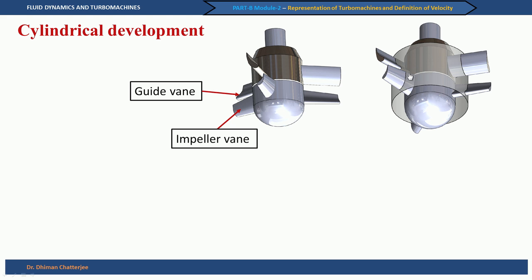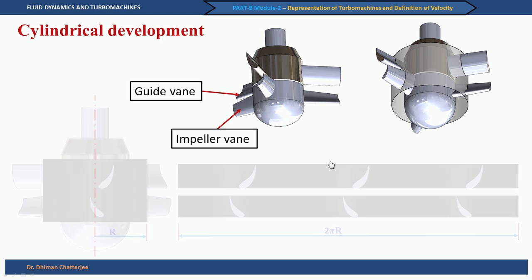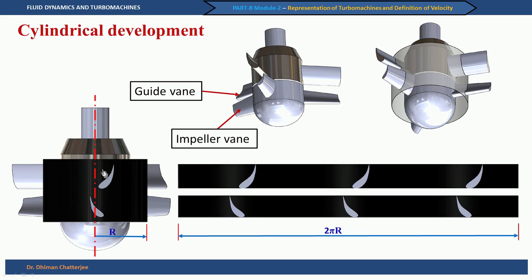To look at it more closely, this is a portion of the paper just shown, which is wrapping around the axial flow machine, and when the blades cut and come out through the paper, this paper will have a shape cut out, which is the shape of the aerofoil profile at that radial location.